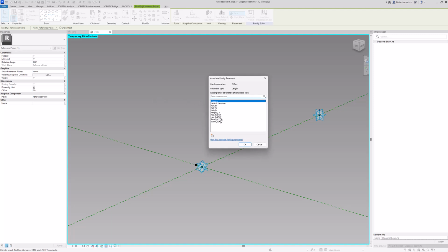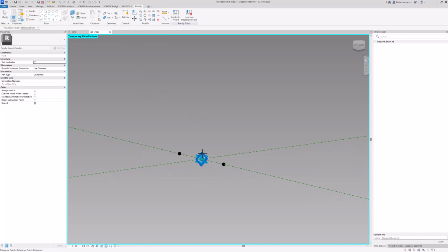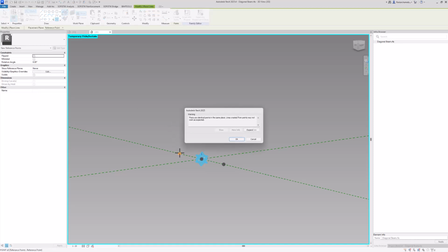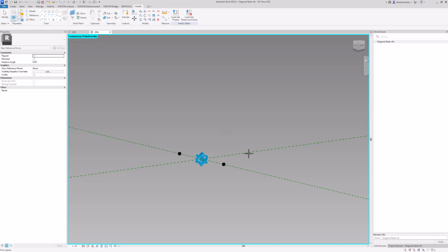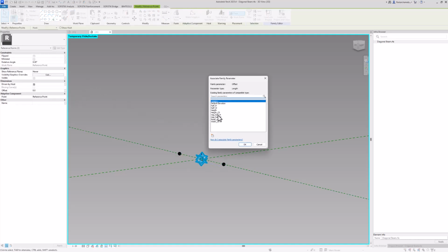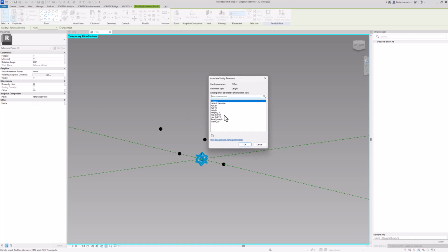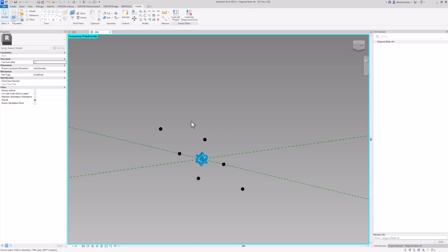Negative half width. And now zoom in and go to the height, which is once more the plane which rotates with our original rotation point. I select two of the points I just created to be quicker, where I select half height, another two, and I select negative half height. I link them together to get my rectangle.